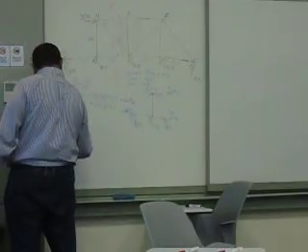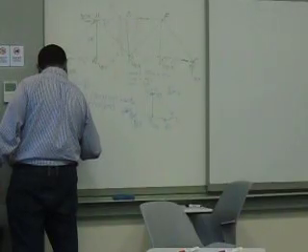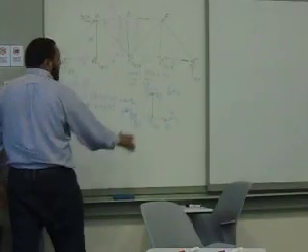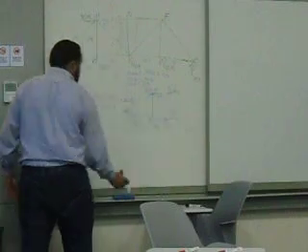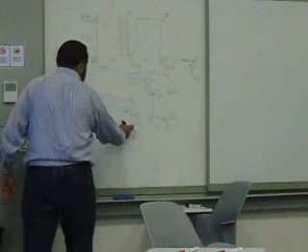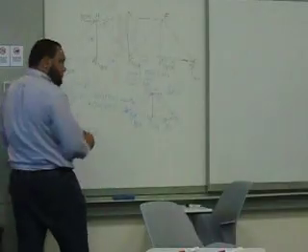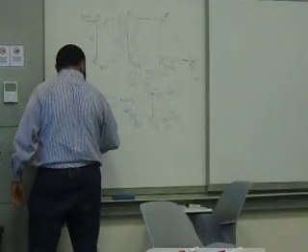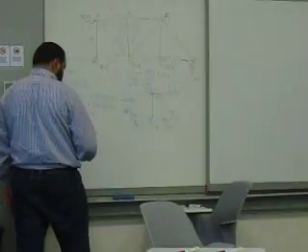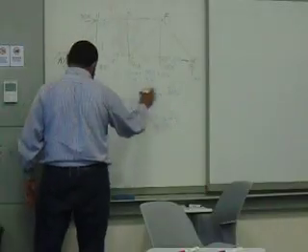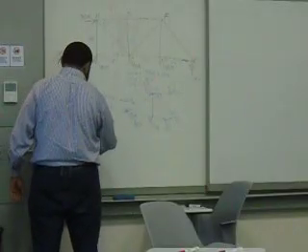After that I'll do sigma Fy equals 0, equals the vertical component of FHC, the 40, and the reaction together. So I'll have here the 50. Yeah? 7.5, negative 7.5? No, I put this on the other side. No, yes, positive 7.5.